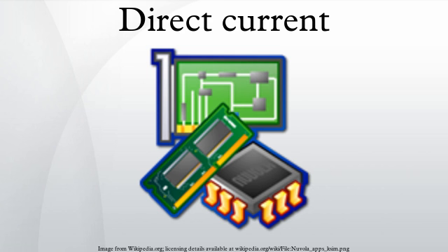Many telephones connect to a twisted pair of wires, and use a bias T to internally separate the AC component of the voltage between the two wires from the DC component of the voltage between the two wires. Telephone exchange communication equipment, such as DSLAM, uses a standard 48V DC power supply. The negative polarity is achieved by grounding the positive terminal of the power supply system in the battery bank. This is done to prevent electrolysis depositions.